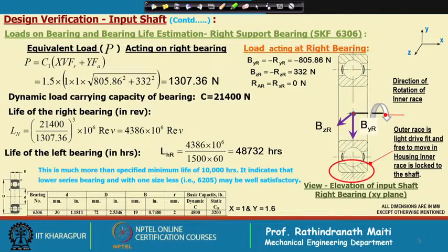That seal is available almost every 2 millimeter. So, that means if we take a bearing of 25 millimeter inside, probably we can make the shaft diameter for the oil seal 24 millimeter and the shaft diameter probably 22 millimeter or even 22 and a half millimeter.